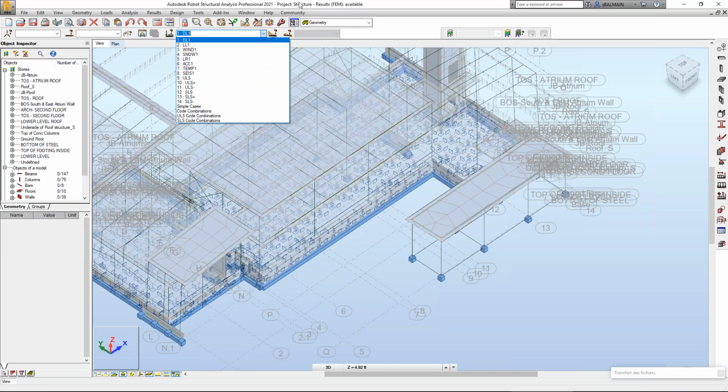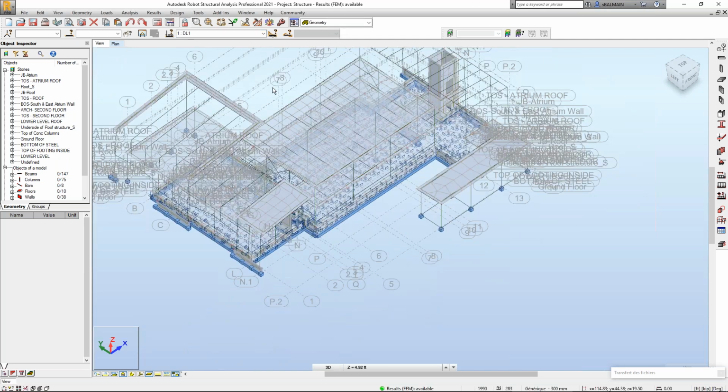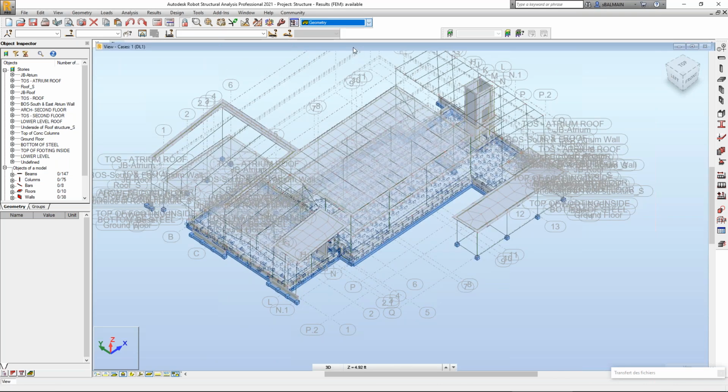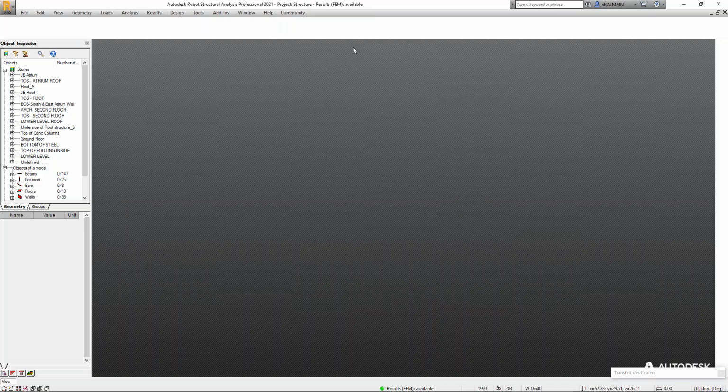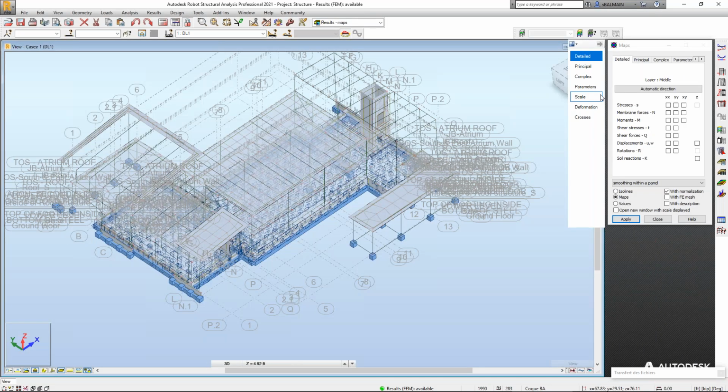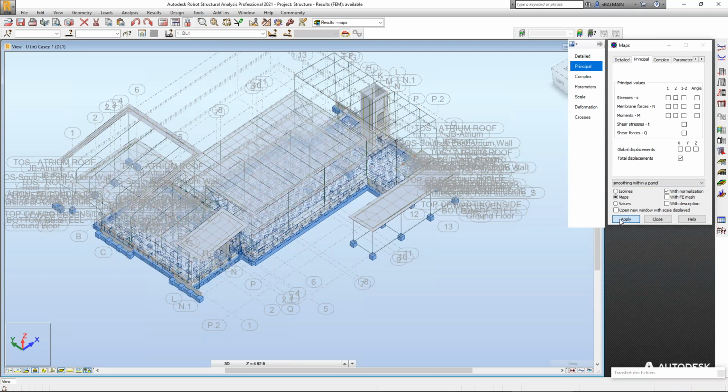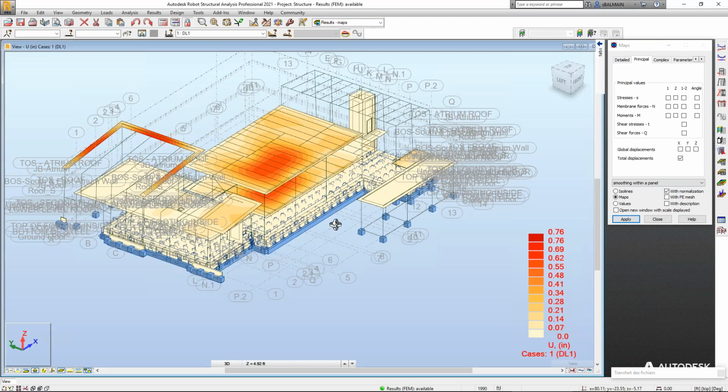So at first, when you have this, what is my first thought? Because all the bending moment and shear come from displacement, I usually check my displacement. So here I will check first on shell to look. And here, for example, if you have a really strange value, it means that something is not connected the way you want, I would say.